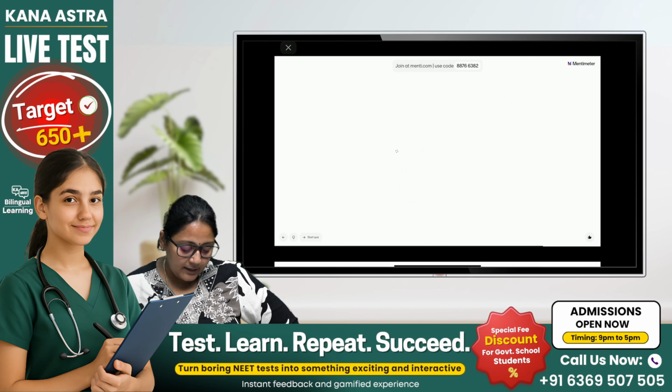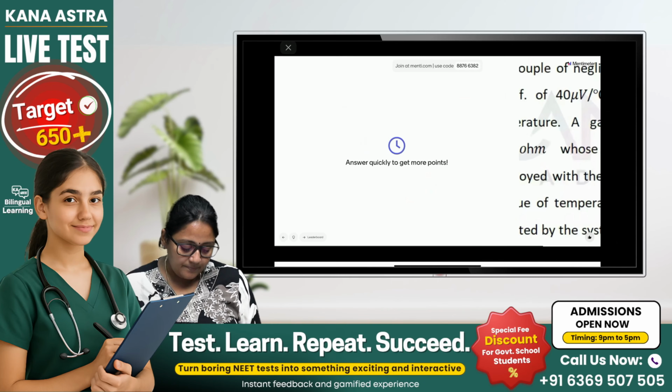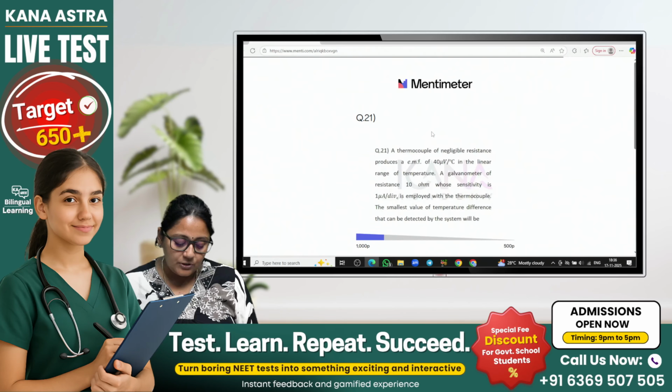And the next question is, a thermocouple of negligible resistance produces an EMF of 40 microvolt per degree Celsius, the linear range of temperature. The galvanometer of resistance 10 ohm, whose sensitivity is 1 microamps per division, is employed with the thermocouple.